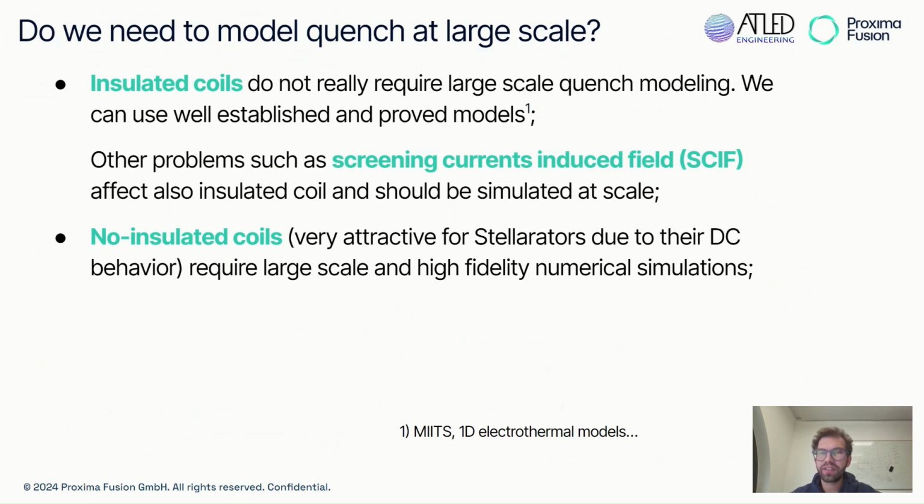And in short, when it comes to insulated coils, it's not really the case, because as most of the community is aware, we can use well-established and proven models like MITs, electrothermal models, lumped models, and so on. But then there are other problems such as screening-current-induced field, which are very problematic for field quality, or induced stress, that require 3D simulation.